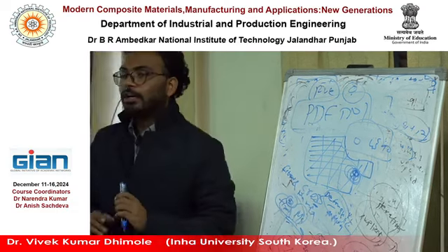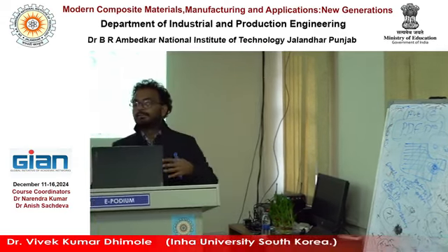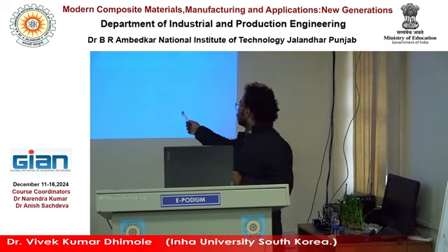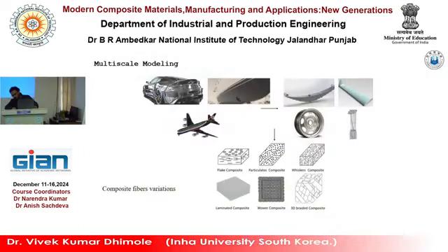So this is a way to work with composites, like lamina composite, particulate composite, whisker composite, woven composite, braided composite. Nowadays, woven and braided composites are the key structures because they have started being used in turbine blade systems and also in complex systems like the wing system. Because they can handle bidirectional stress, they can compensate for each other. So this is the advanced composite, right?